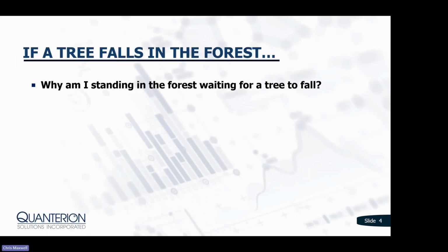This is sort of a pun of a question that I asked myself about condition-based maintenance, as in comparing a part failure to a tree falling. One of the main things is trees generally fall without warning. Condition-based maintenance is generally predicated on having warning, which is usually conceptualized as the PF curve. Some failures have warning, some failures don't. Sometimes you'll stand a long time listening, and you might not know until it's already failed.